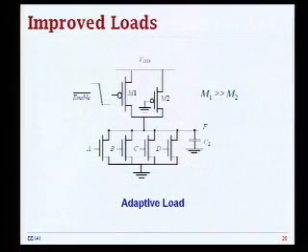You can also adjust this PMOS load. This is one technique that is common in design practice. Sometimes I need to really shift this VTC. Sometimes I'm more worried about performance, sometimes more about static power. So you can adaptively change the load depending on what you need to do, whether you need to make a transition or just stay in the steady state.